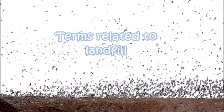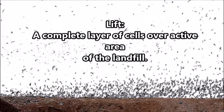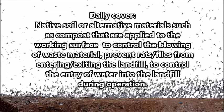Terms related to landfill. Cell: the space occupied by the waste material in a landfill during one operating period, usually 1 day. Lift: a complete layer of cells over the active area of the landfill. Cover: they may be native soil or alternative materials such as compost that are applied to the working surface to control the blowing of waste material, prevent rats and flies from entering or exiting the landfill, and control the entry of water into the landfill during operation.